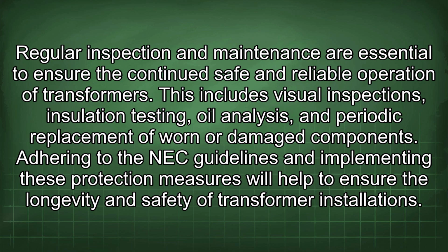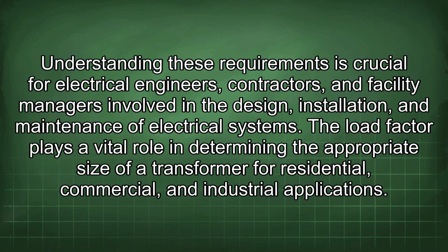This includes visual inspections, insulation testing, oil analysis, and periodic replacement of worn or damaged components. Adhering to the NEC guidelines and implementing these protection measures will help to ensure the longevity and safety of transformer installations. Understanding these requirements is crucial for electrical engineers, contractors, and facility managers involved in the design, installation, and maintenance